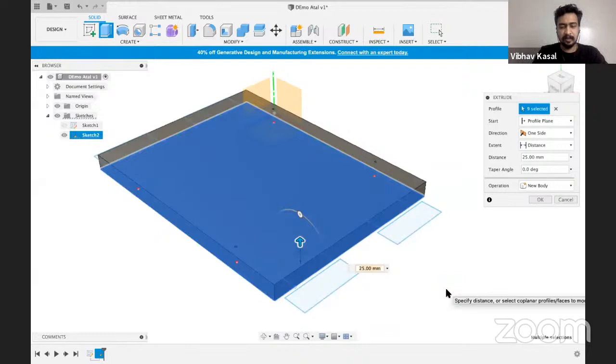Okay, so I'm laser cutting it. From experience, I can tell it can easily laser cut anything which is very thin, say 1 mm and above. If it is less than 1 mm, you will see the material will get bent and warped and all sorts of things. It is a different case, you can cut even thinner things as well, but it might catch fire if it is very thin. The burn marks will take out more material. As the thickness increases, the burn marks from the laser is also something that we have to consider.